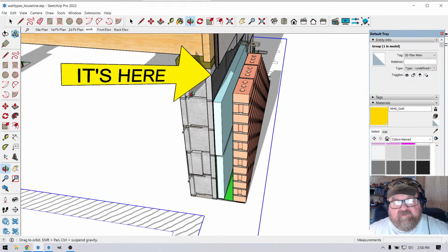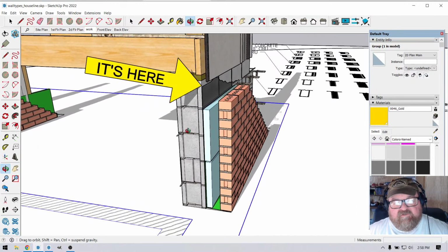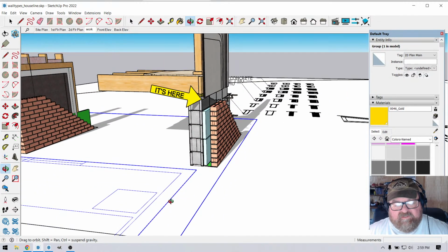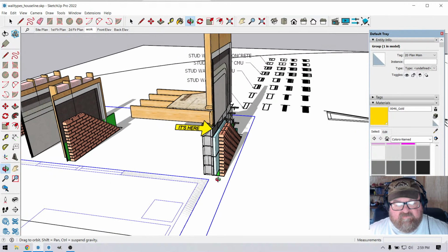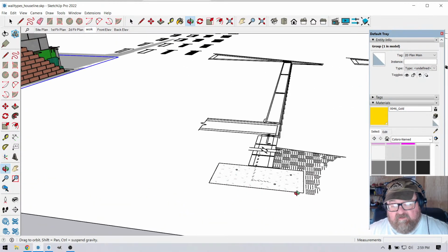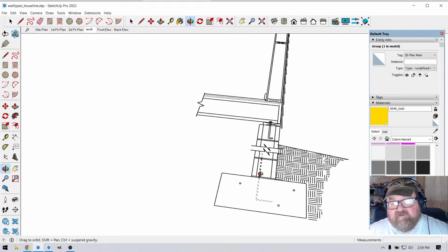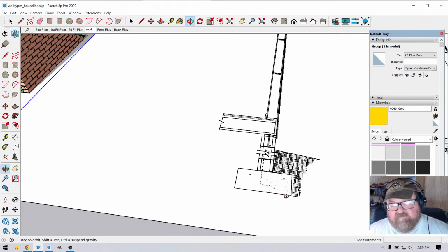So think about the sequence of the operation here, the order of construction. The first thing you do is, like I said earlier, you pour. You have your footings spotted on the ground by your surveyor, and then we come out and dig them. You can see here the footings are wider than the foundation, and that's typically based on the number of stories, basically the load that you're putting on this ground here per linear foot, okay?